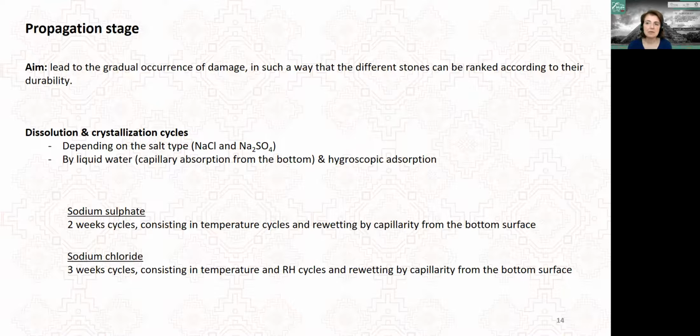So the test for sodium chloride consists mainly in those cycles, plus a re-wetting by capillarity from the bottom surface in order to retransport the salt towards the surface, because during these relative humidity cycles, some redistribution in depth of the salt was observed.